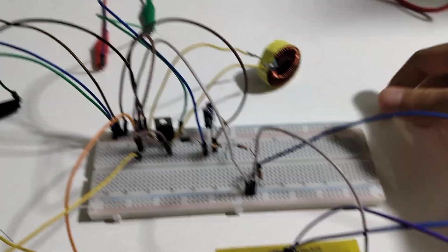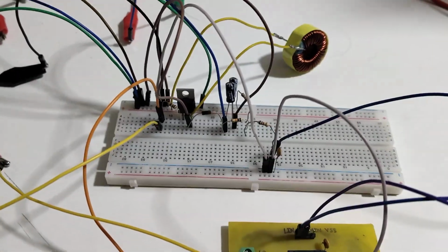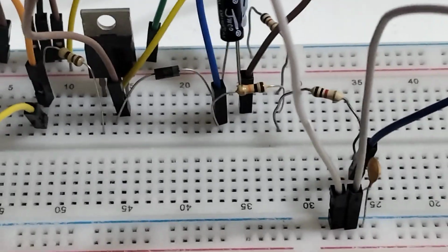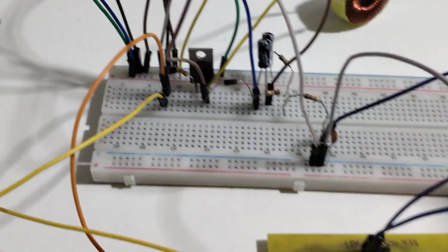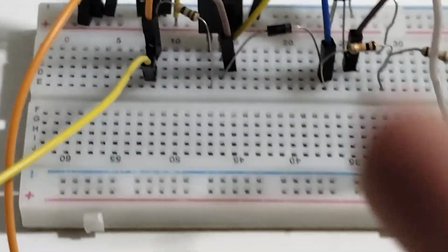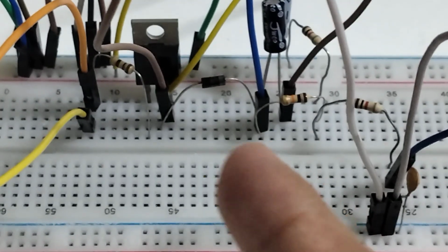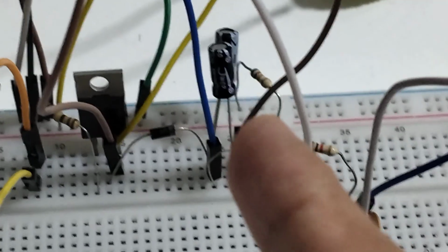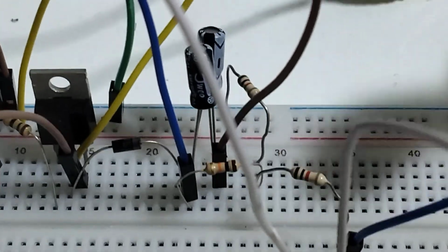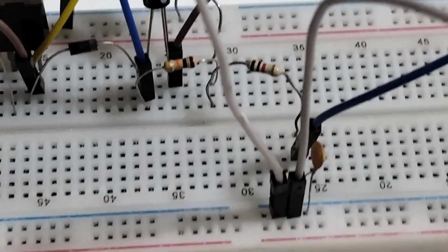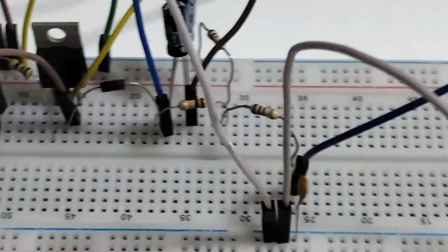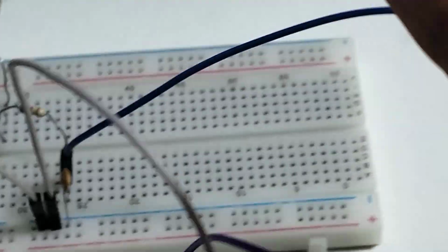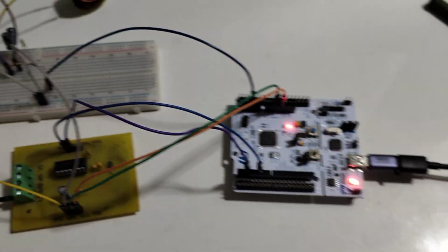And again, 100 kilohertz on a breadboard is probably a bad idea, but for just showing you how the power converter works, there are a lot of limitations, but it should be fine for now. We have the MOSFET, the gating resistor, that's the diode, and our capacitor. And as I said, we need the resistor divider, right? So we have a 10k and 1k to scale down the voltage. And after that, it's just a low pass filter of 1k and 100 nanofarad to remove all the switching ripple. And that goes to our ADC pin over here in the microcontroller.